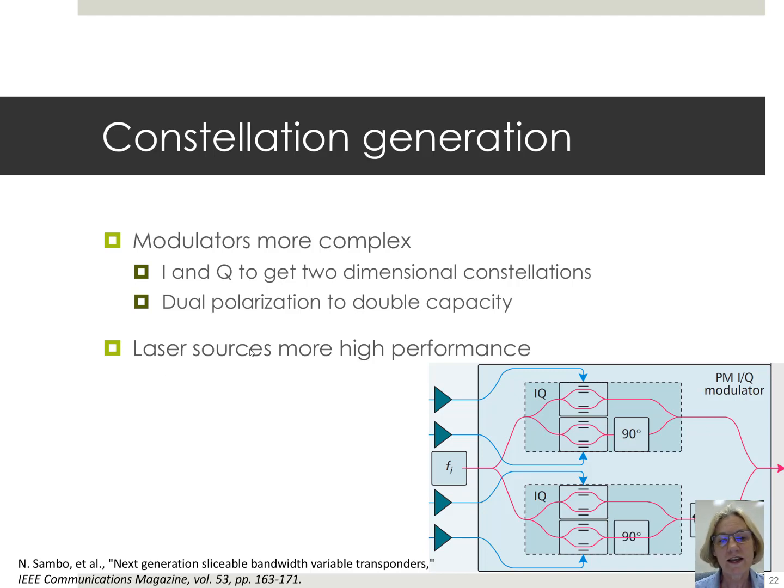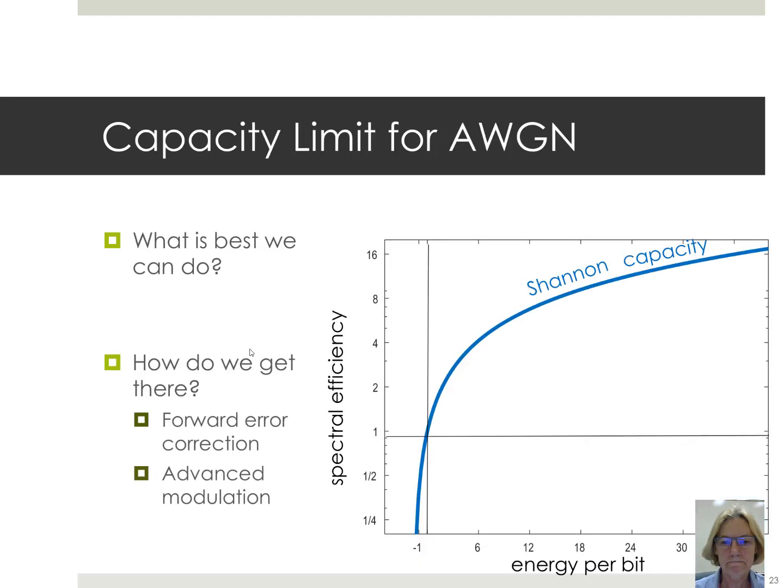The noises in phases of the laser source would make it very difficult to detect differences in phase. And so we need laser sources with what we call a very small line width, or on whom the native phase is fairly stable.